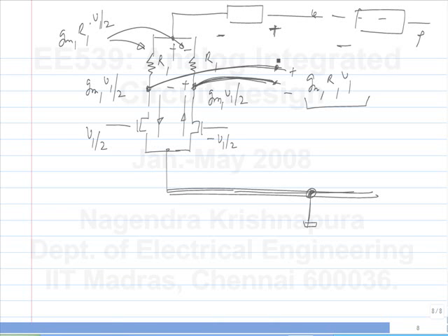The reason something like this is not used in discrete circuits is cost, because you will end up with twice as many wires, twice as many components and so on. Whereas on an integrated circuit, the cost is not measured by the number of components, but the total area. We'll see that afterwards, but you can make each of the components half the size, but double the number, then it doesn't make a difference to the IC. In fact, you are getting a performance advantage. So generally on an IC, you have fully differential circuits, and with discrete component circuits, you will have single-ended circuits. But it is much harder to make single-ended circuits noise immune and have very high dynamic range and so on, whereas it's much easier with a fully differential circuit. Any questions?